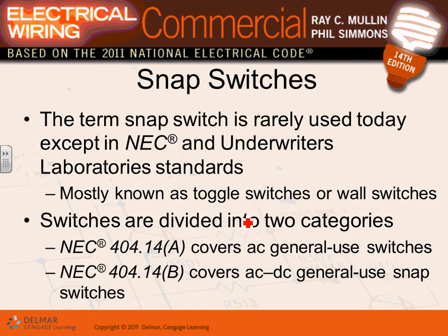So to summarize, you need GFCI protection for receptacles in a commercial building. Typically, any place that has a wet location has to be GFCI. You use something called spec type receptacles, more expensive, more robust, capable of being abused more. For technology circuits you use so-called isolated ground receptacles with an isolated insulated grounding conductor.